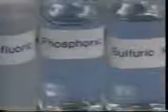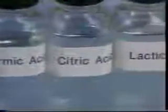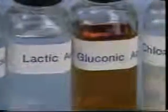The inorganic acids, like hydrochloric, hydrofluoric, and fluoboric, are considered strong acids because of their ability to dissolve a relatively large volume of solids with a small volume of liquid. On the other hand, organic acids, any acid containing carbon, are generally considered weak acids. Their main advantage is that they are less corrosive to metals than HCl or HF acid. Therefore, organic acids are particularly useful in the treatment of carbonate formations where temperatures are extremely high or where contact time will be relatively long. Note, however, the inability of the commonly used organic acids to dissolve silica or clay material.